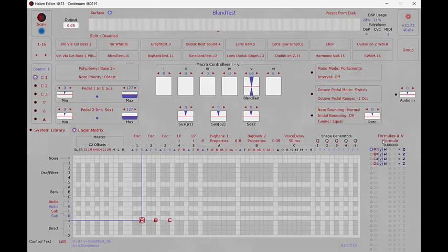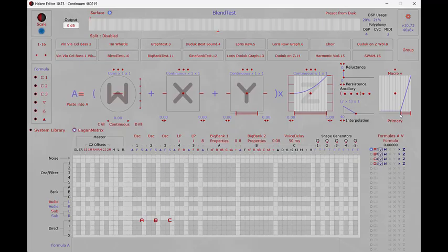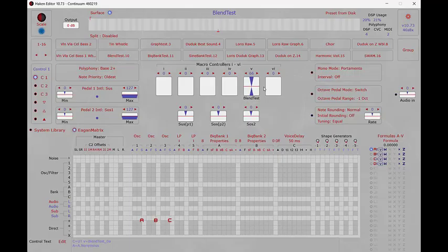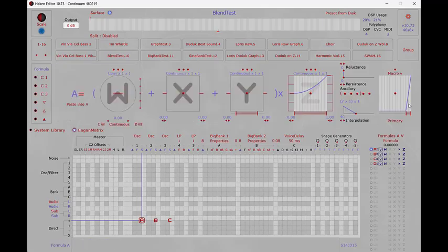Let's add even a little more hysteresis there. We'll start here, and you'll see now it's going to take a lot longer for my increase to start kicking in. There, it doesn't kick in until almost 3/4 of the way through. So by manipulating this blend offset, you can impose some hysteresis, some lag, and that's going to be helpful because your roll might never exactly be on 0.5 or your midpoint value. Same thing with yaw. By putting a little hysteresis in there, you can move a little bit and you'll still be remaining on your 0 value, giving you a little bit of leeway before your roll or yaw kicks in.